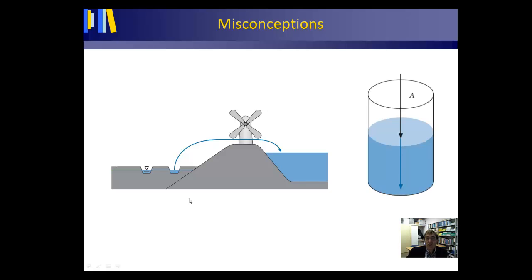In actual fact, you already knew that water does not necessarily, by law of nature, need to flow from high to low water pressure. If you look at the water in this cylinder, the higher water pressure is here at the bottom and the lower water pressure is here at the interface of the water with the air above. The water is at a standstill in this model. It does not, by law of nature, flow from a higher water pressure to a lower water pressure.